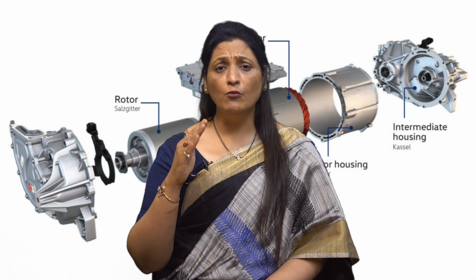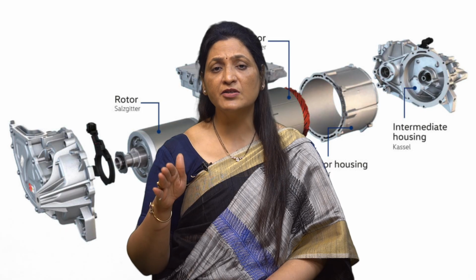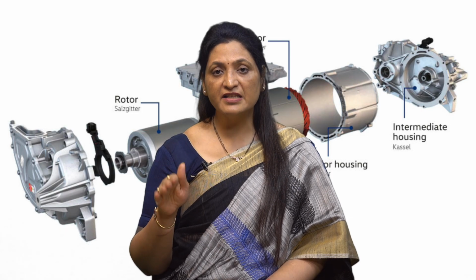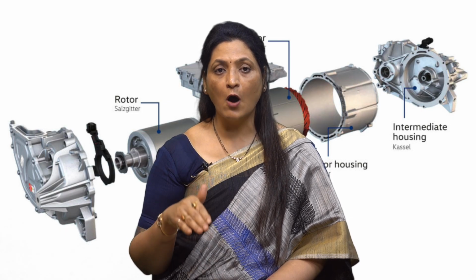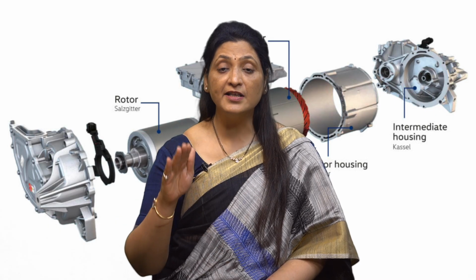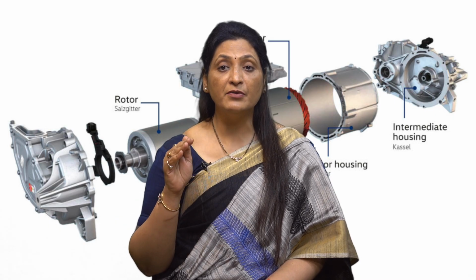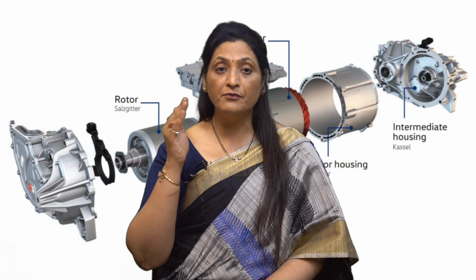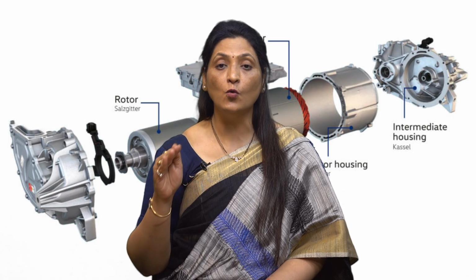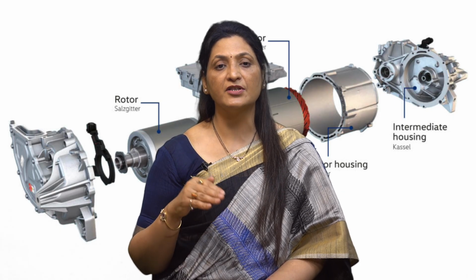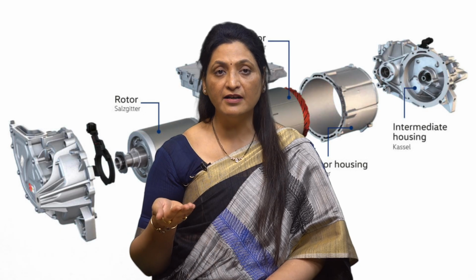Thus, if a motor is rated continuous 10 HP, it means that it is capable of giving an output of 10 HP continuously for an indefinite period and 12.5 HP for a period of 2 hours without the temperature exceeding the specified limits.